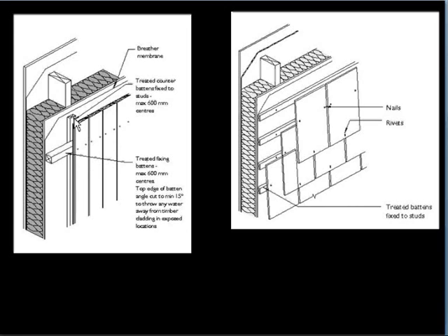The purpose of having two battens, and usually this batten has an edge that slopes away, is that we need to make sure that we've got a cavity behind, so that any rainwater doesn't lie on top of this batten but drains off the back of the batten and down through the cavity and out of the construction.